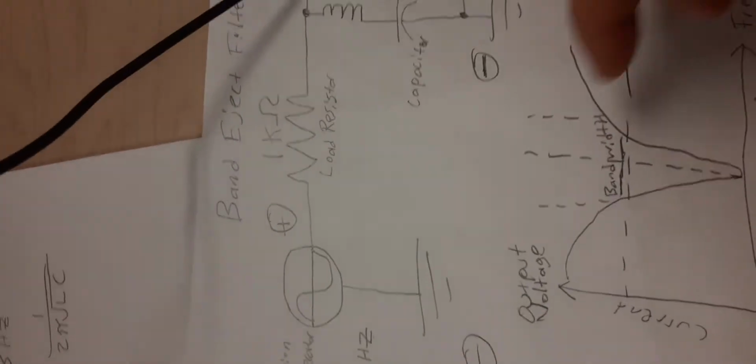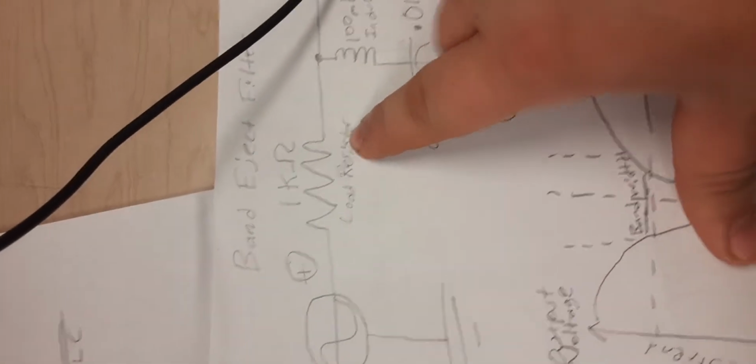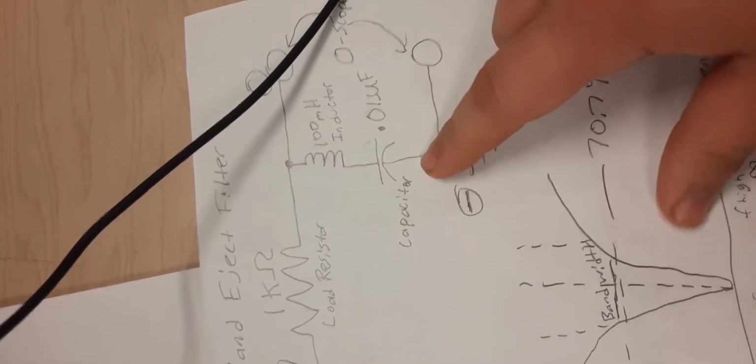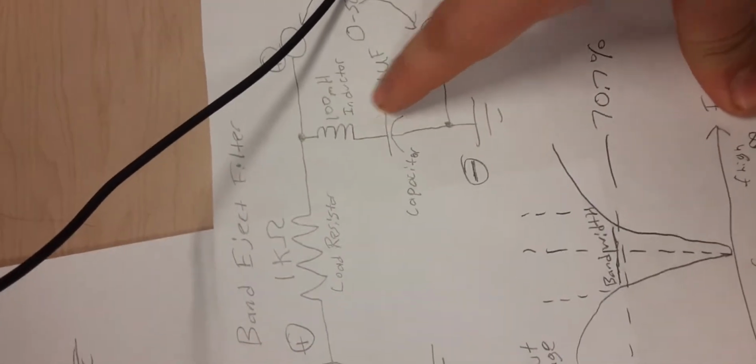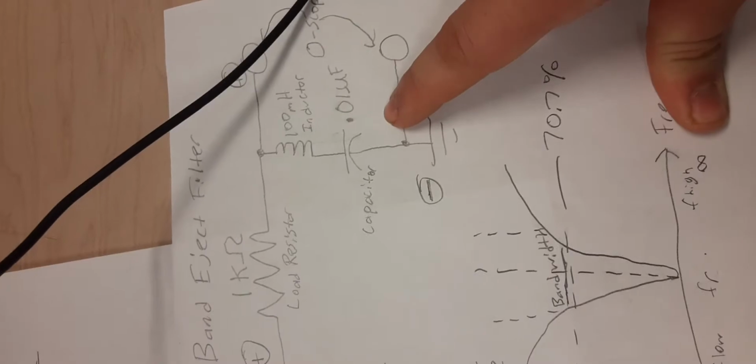And then to find impedance, now that I have those values, I can find that. That's my resistor value, which is a 1K ohm resistor. So I have my resistor value squared plus my X of L minus X of C, and that's squared, so that's just 1,000 ohms. Okay, so on our schematic, we have a 1K resistor going to a 100 millihenry inductor, and then a 1 picofarad capacitor.